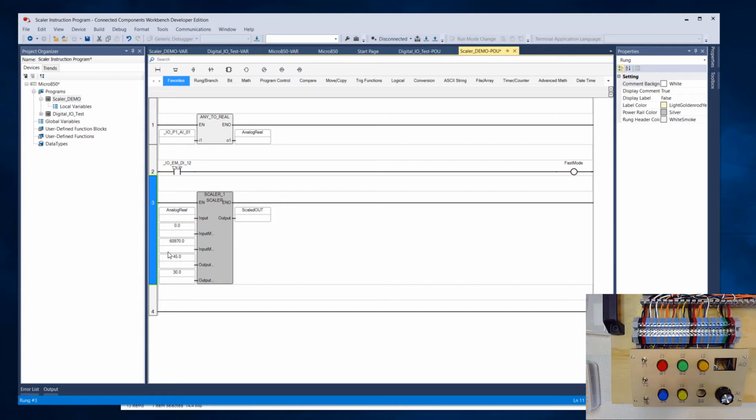If you think back to when we were talking about analog, this input max, if we were going all the way up to 10 volts, would be up at 65,536 roughly. But since our voltage range is only 0 to about 9.4, our max is 60,970, and we're taking care of that right there. So we're not going to mess with those unless something changes about our hardware input. We're mainly dealing with the output variables.